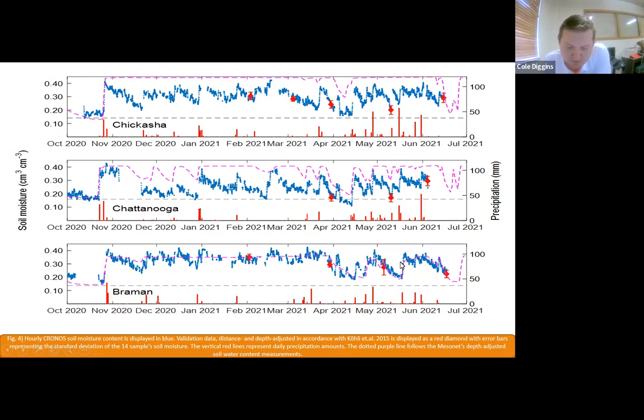And then third that I'd like to point out is the permanent wilting point right here in April. So if you see that, our soil moisture dipped below the permanent wilting point at this point in April. And I really want to put that into your mind real quick, because I want to come back to it here in a moment as we look at our green canopy cover.